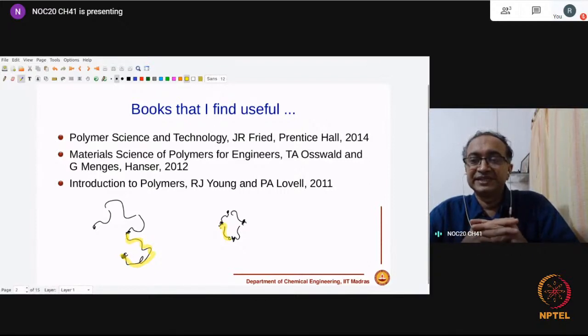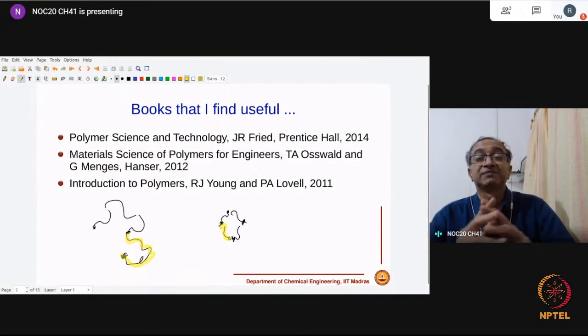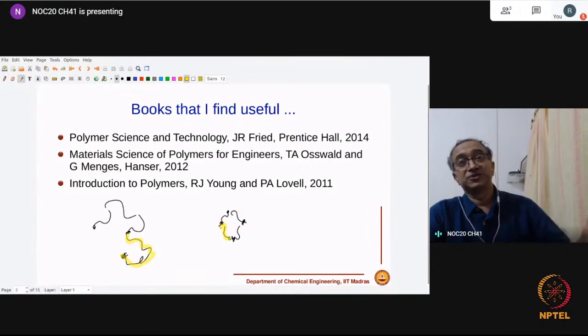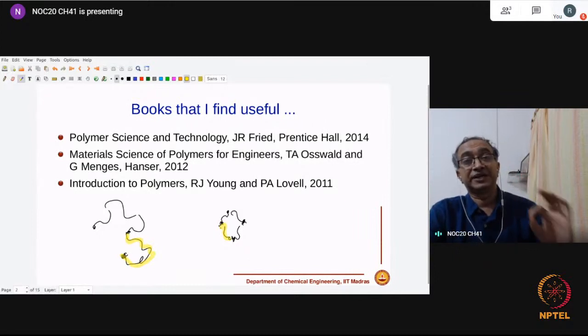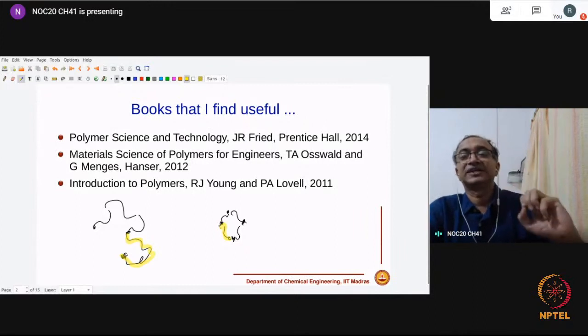Durga Pawan is asking, is there any polymer which has a cross-linking structure but is mechanically recyclable? That's in fact mutually exclusive, right? Because whenever you have done cross-linking, you have linked all the molecules together, so it's an infinite molecular weight. Everything is linked in a cross-link network.